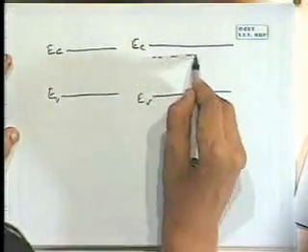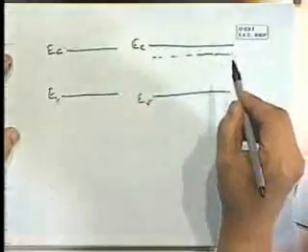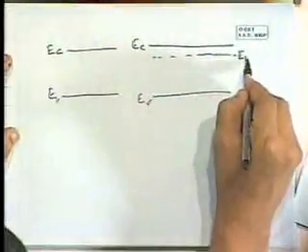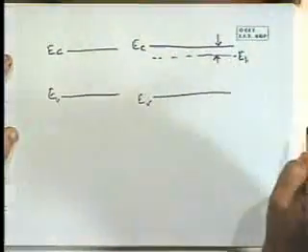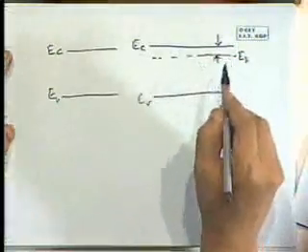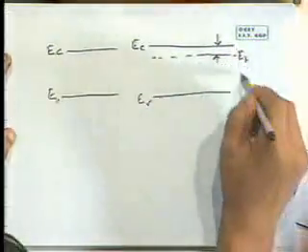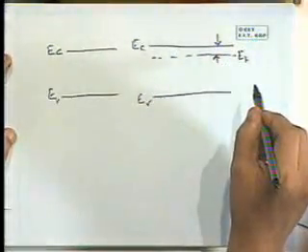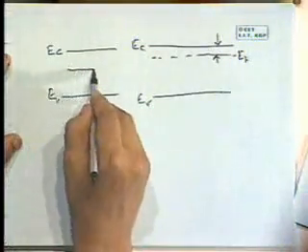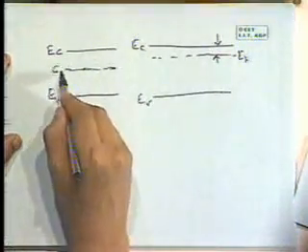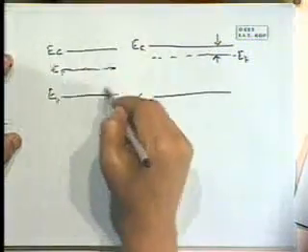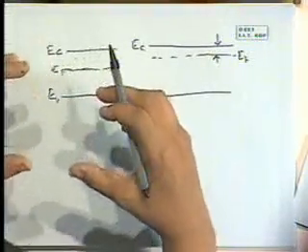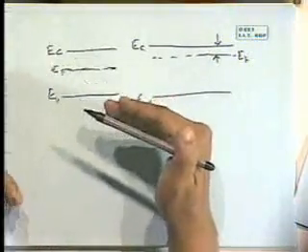There's a standard N-type material with certain carrier concentration with EF this height. Now, I remove some electrons. What will happen to this gap? It will increase, right? So let's draw it here roughly. This is the case where there are fewer electrons, so the EF has shifted with respect to EC.